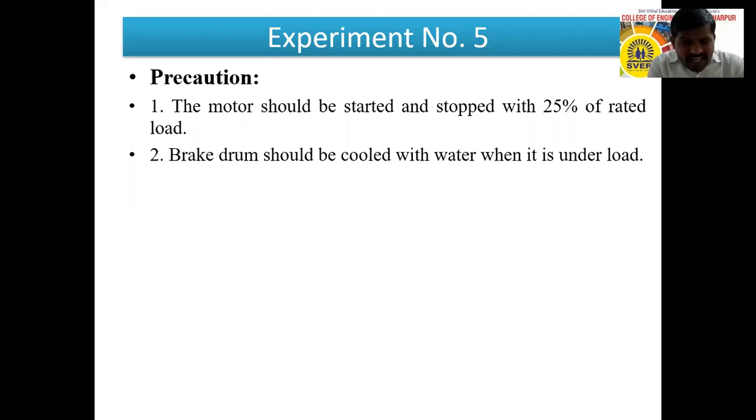Due to the high speed and high starting torque of the motor, if we are directly applying mechanical load by using a belt and pulley arrangement, there is friction. At high speed there is more friction, so there is maximum heat dissipation, right? Maximum friction असल्यामुळे त्याच्यामध्ये heat dissipation जे असेल ते maximum असेल.